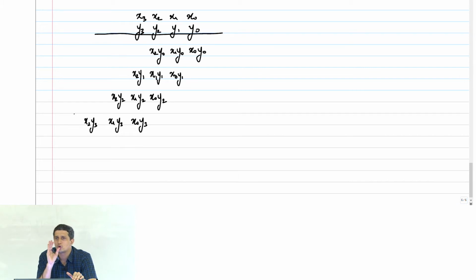You have to take the 2's complement of that number, which means you invert the bits and add 1 to it. So I will invert these numbers. Of course, these were zeros earlier; I am going to now make these 1. Similarly, there are the x3y0, x3y1, x3y2 terms, which will come here.